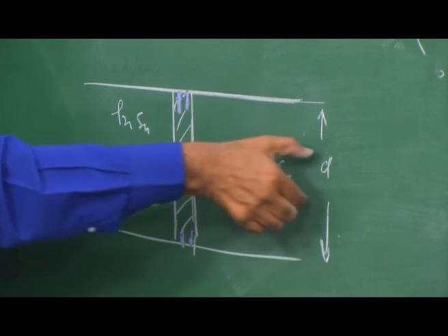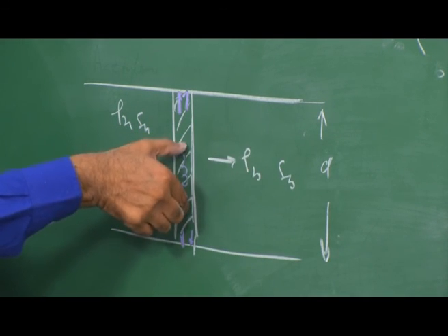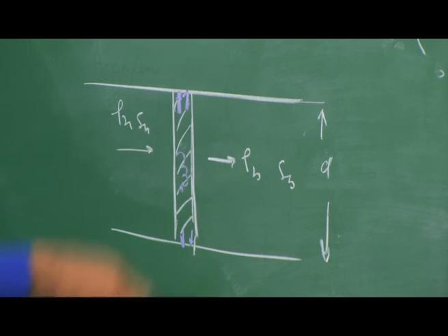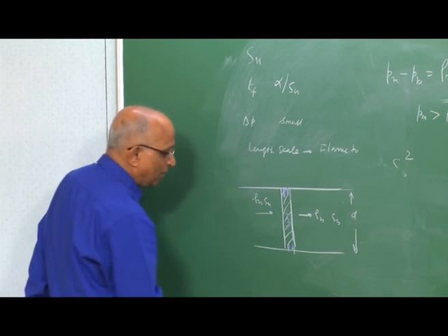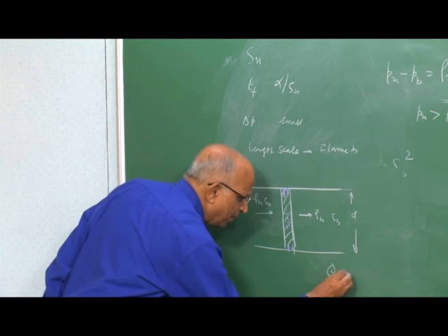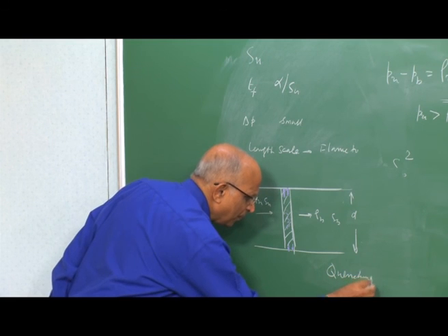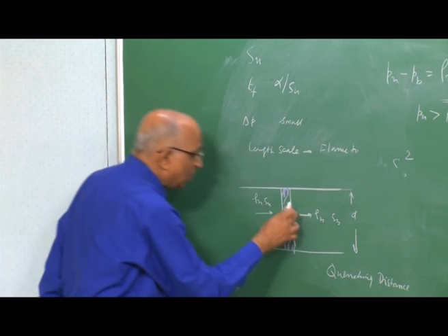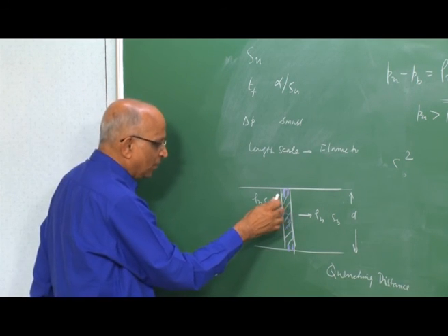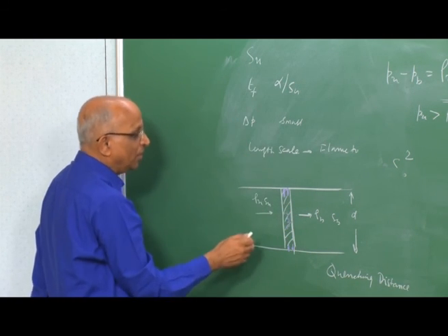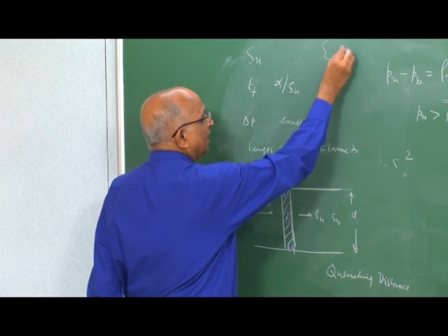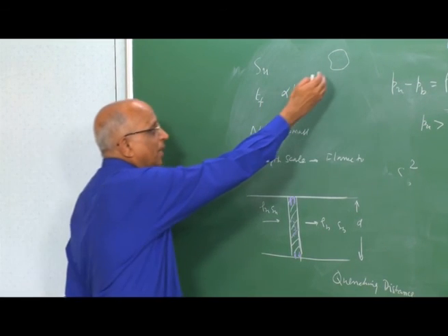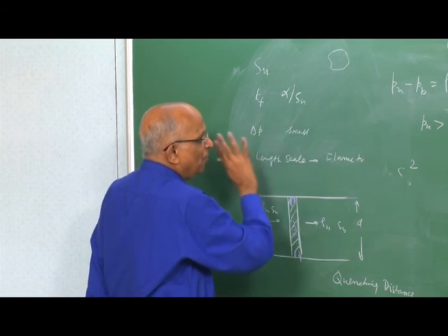Is there something like a diameter below which the flame cannot propagate, or rather a diameter by which the flame will get quenched? Therefore, what I will do is, maybe I will take a look at the quenching distance or a quenching diameter, and based on this quenching diameter, I will put the quenching diameter along with flame speeds to be able to define something like the critical size of the ignition kernel. I will follow this up in the next class.